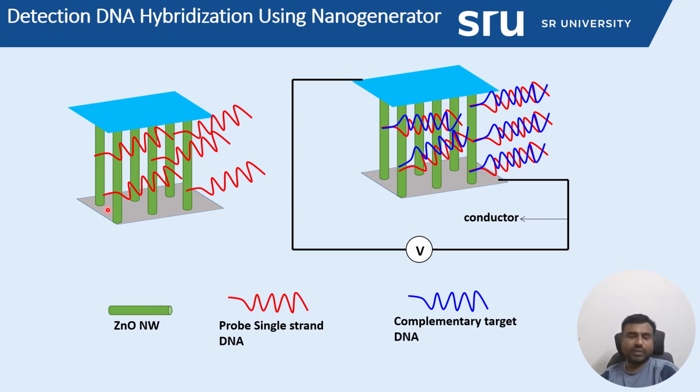Compared to the conventional approach, what will happen? We have to perfectly clean the electrode, then put some bioactive layer, nanoparticle or metal-based material over the transducer surface, followed by attaching the probe single-strand DNA over the electrode surface. The attachment also plays an important role in getting a perfect signal. So these processes are highly sensitive, and repeatability is really a difficult task. After attachment of the probe single-strand DNA, we allow either complementary, non-complementary or mismatched DNA.